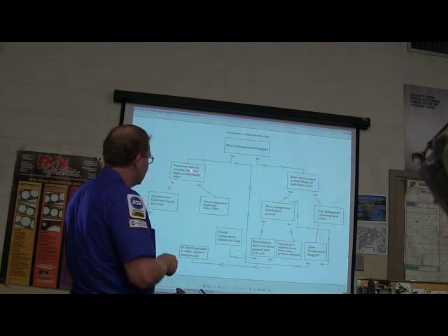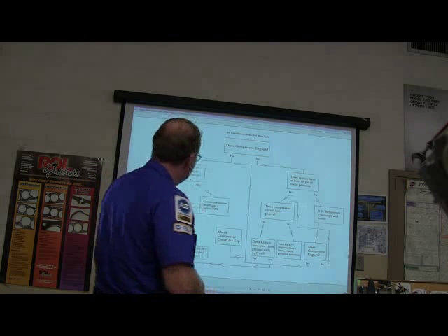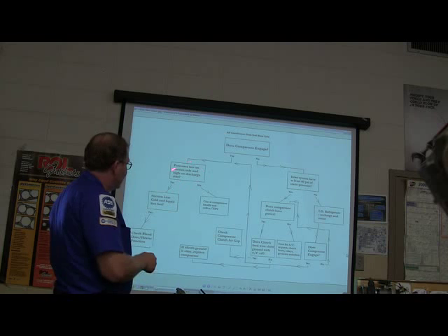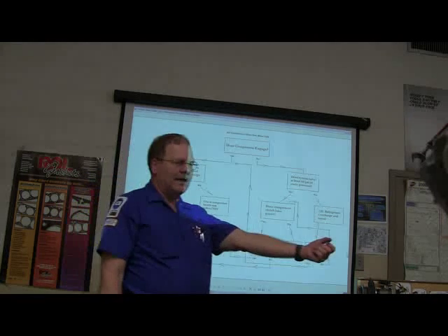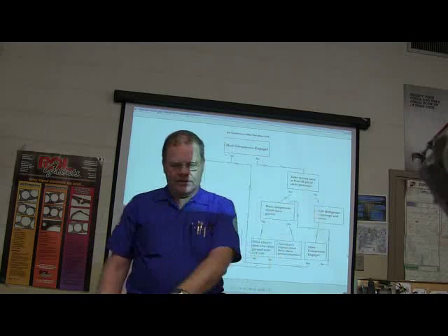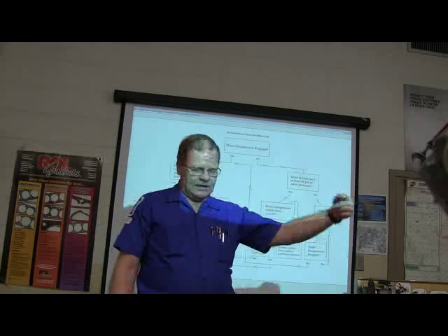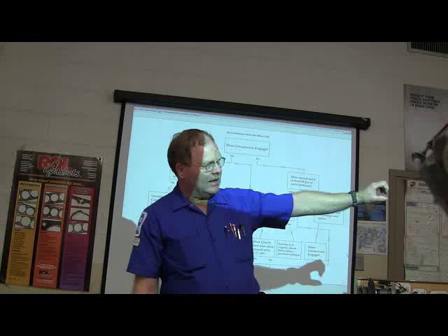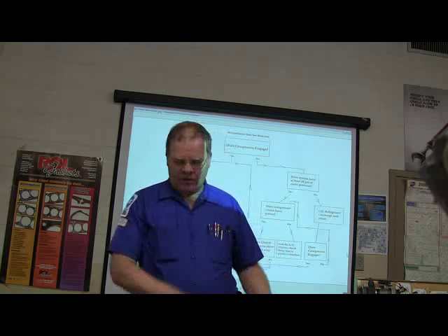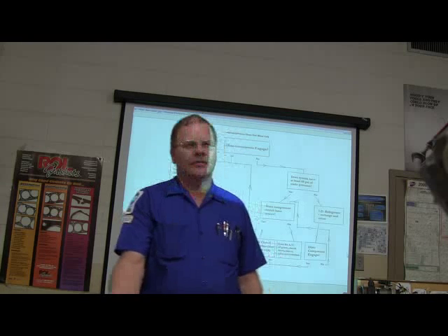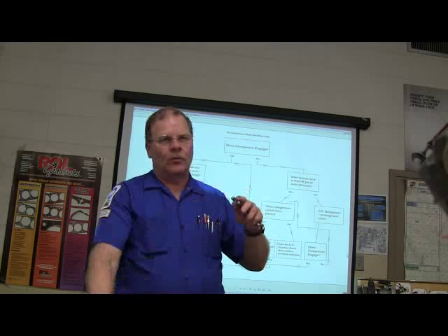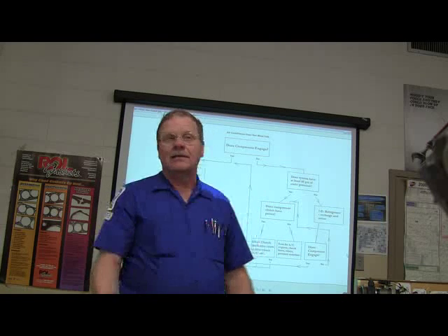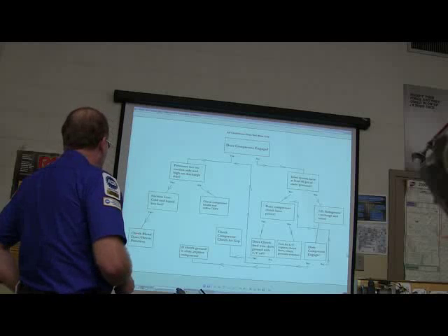All right. But if the compressor engages, that's a yes. Are the pressures low on the suction side and high on the discharge side? If that's true, you're going to feel the suction line. Is the suction line cold and the liquid line hot? Suction line is the big line that comes from the firewall and goes down into the bulkhead, down into the compressor. That line should be cold through the accumulator, if it's got one, all the way to the compressor if you've got enough refrigerant in there. If it's cold coming out, but it gets warmer and warmer as you go, then that typically means that you don't have enough refrigerant in there.